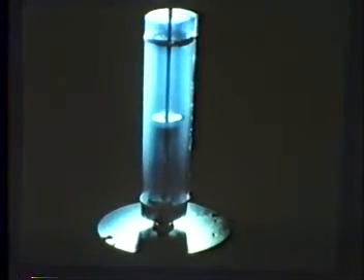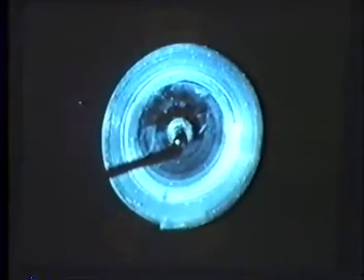This is the spiral. The Melinex strip was 1 meter long, 6 centimeters wide, and as we said, 6 microns thick. It contained 20 turns, inner diameter 10 millimeters and outer diameter 18 millimeters. You see the structure of the spiral more clearly looking at it end on. It's really very uniform. You see 1 or 2 paper shims which we had to use to keep the spiral winding true. The spacer ribbons were 0.5 millimeter wide, and they were a bit troublesome as well. It's all tacked together with nail varnish, and although it looked stable, it was extremely fragile.